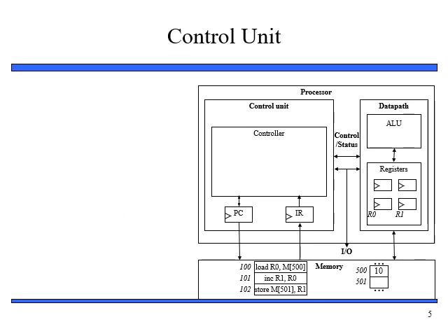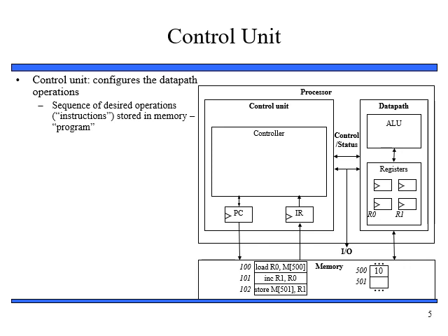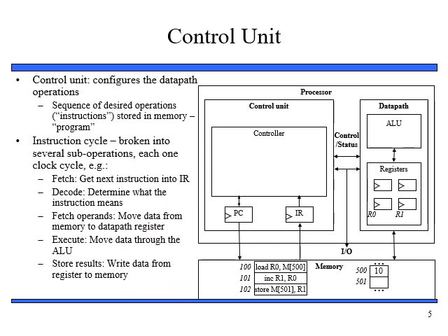So in this slide we are going to talk about the control unit. The control unit consists of circuitry for retrieving program instructions. The program counter holds the address in memory of next program instruction to fetch. Instruction register to hold the fetch instruction. Now controller consists of state registers and control logic as we saw in chapter number 2. Now for example, if we have a 16-bit program counter, it means that we have 2 raised to power 16 memory location.